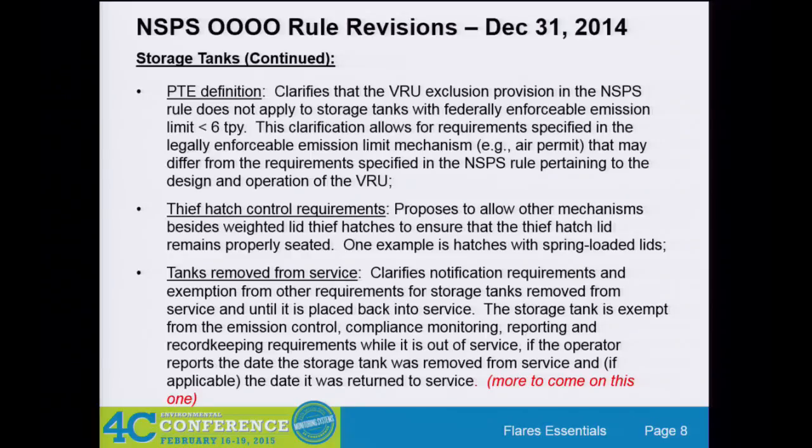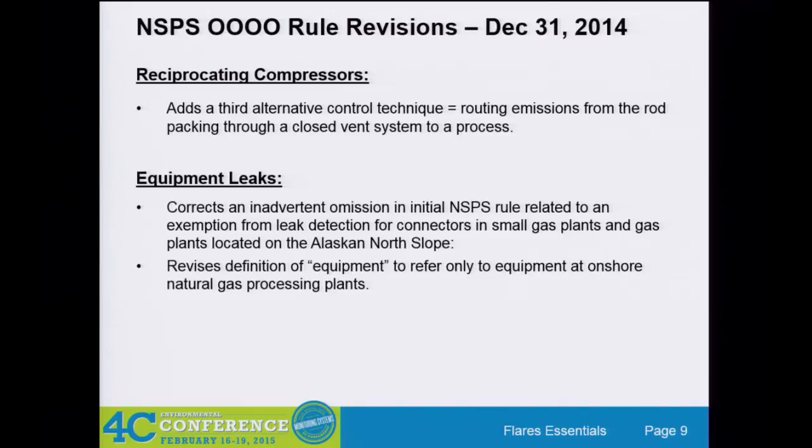I'll come back to this in a minute, but this is, I think, the confusing part of the new rule. It has to do with removing tanks from service and bringing those tanks back into service, which happens a lot in the industry. As wells deplete, you may shut in the well for a period of time. You don't have to comply with the rule if you empty that tank and degas it. Completely makes sense. But when you restart the well and you may refrac it, you've got to be ready to bring those tanks back into service and be in compliance pretty much on day one. So they added a lot more language around removing and adding tanks back into service, which I'll talk about more in a little bit.